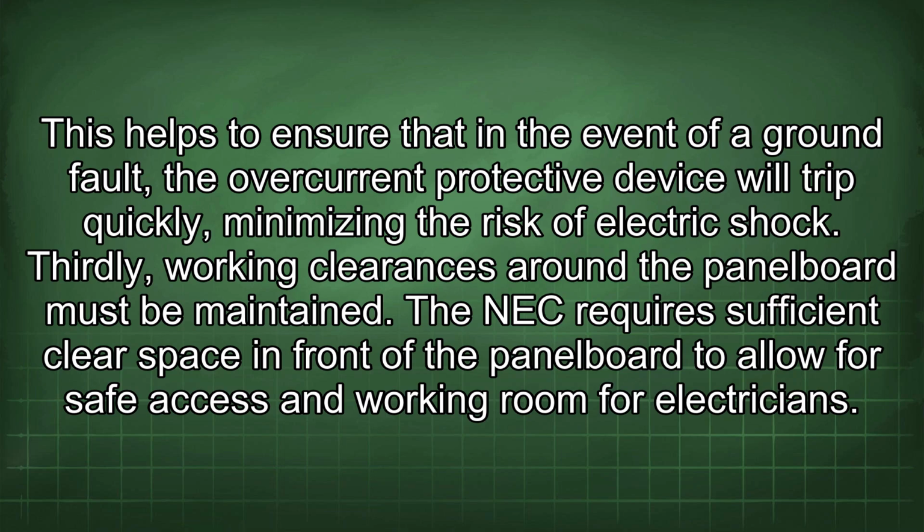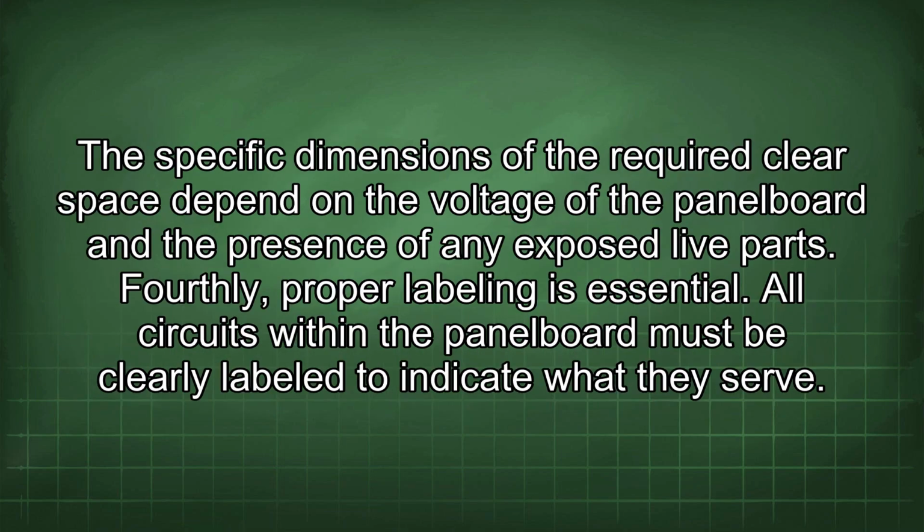Thirdly, working clearances around the panel board must be maintained. The NEC requires sufficient clear space in front of the panel board to allow for safe access and working room for electricians. The specific dimensions of the required clear space depend on the voltage of the panel board and the presence of any exposed live parts.